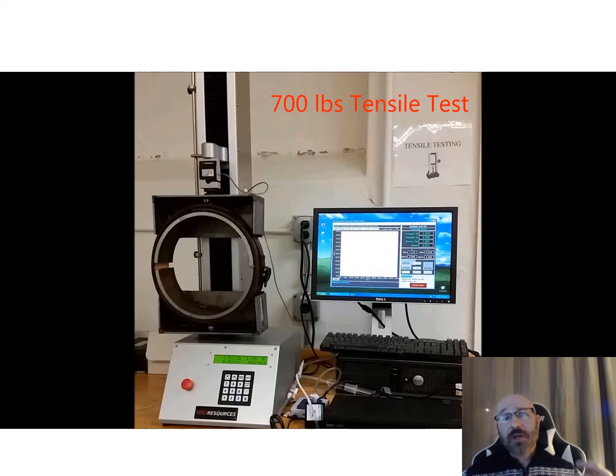And then I needed to correlate those pressures into what type of load I would see here in this load cell on our tensile testing machine, to make sure I got the same practical applications. So what I did was I put the pressure sensors in line with this and watched it, and did some calibration to see, okay, if a lifter had braced off up to a certain pressure, what did that correspond to as a load up here?